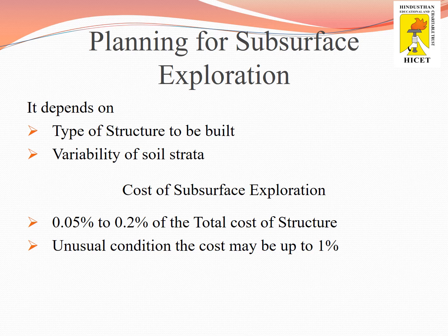A small house in an already built up area would not require much depth of exploration. On the other hand, if the house is to be built in a newly developed area, a detailed investigation should be carried out to know the maximum information about the ground.